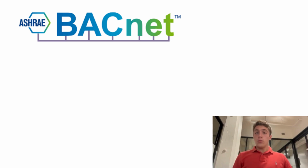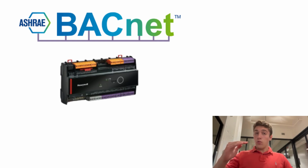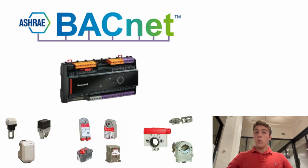So BACnet is the protocol for a system. It's how controllers and devices communicate. Think of it as a hierarchy. Protocol is the highest order, the communication. Then automation devices, such as routers and controllers. Then field devices, which are sensors and actuators and valves. And all these devices act based on orders from controllers, which communicate through BACnet or whatever protocol they're using.